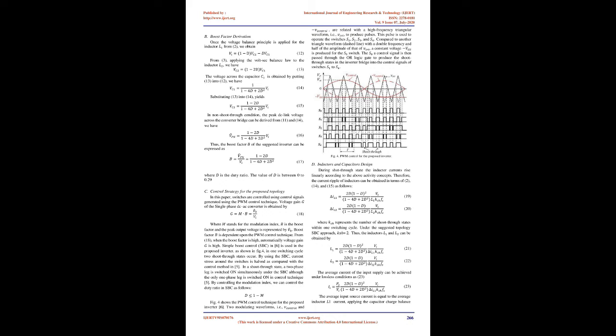2. Non-shoot-through state. Non-shoot-through state conditions are shown in Fig 3b. In this state the switch S and diode D4 are turned off and diodes D1, D2, and D3 are switched on. The source charges the capacitors via the inductors. During this state, power is transferred to the load, which is stored in the inductors. The inverter bridge is open-circuited. In this state, the voltage and current relationship can be written as follows.